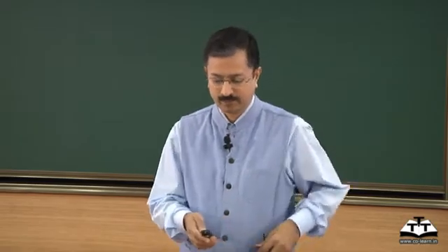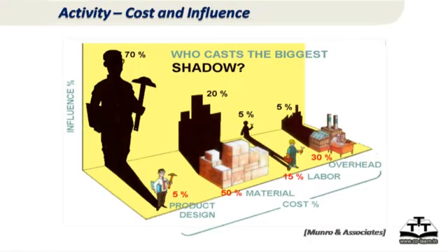casting area. If you look at the 4 different stages or 4 different cost factors in a casting, you have the design cost, and you saw a big one, material cost in the last example. Then you have the labor cost and overheads. So design cost could be 5%, material cost could be 50%, labor cost could be 15%, overheads could be 30%.